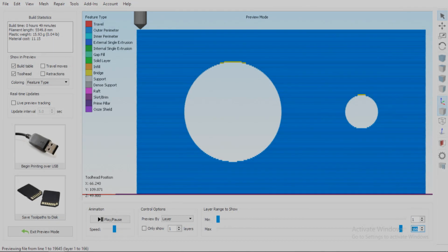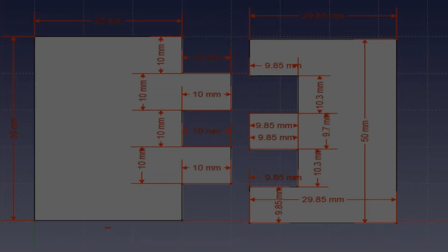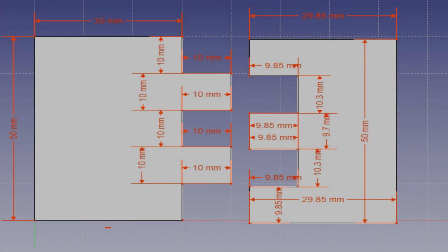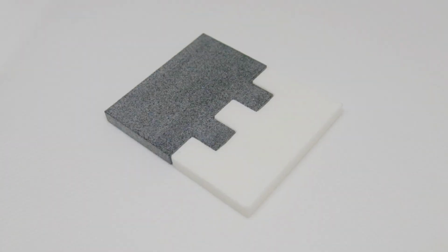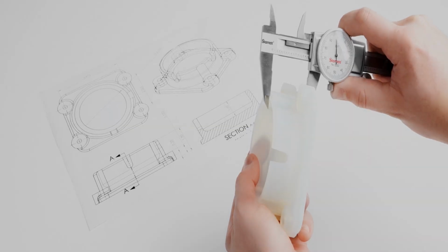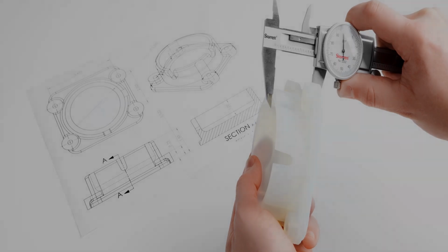A circular hole printed vertically won't be perfectly circular. To achieve a better result, print circular holes horizontally as shown in this picture. When modeling parts that should fit together, you need to include certain tolerance. You won't be able to combine two parts with zero tolerance dimensions. Please keep in mind that you will probably have to tweak the tolerances until you reach an optimal result.